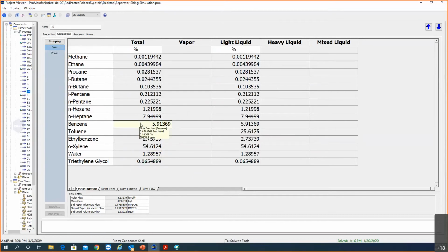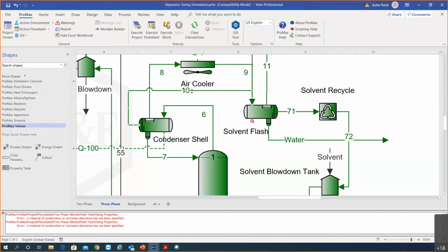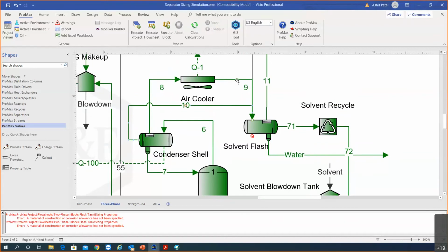For those of you familiar with TEG units, you know that the TEG, while also picking up water, is well known to have a higher affinity for heavy hydrocarbons, and as a result, we end up with those BTEX components. So we have 800 pounds of heavier hydrocarbons going in, and also some water, but not very much in that stream.